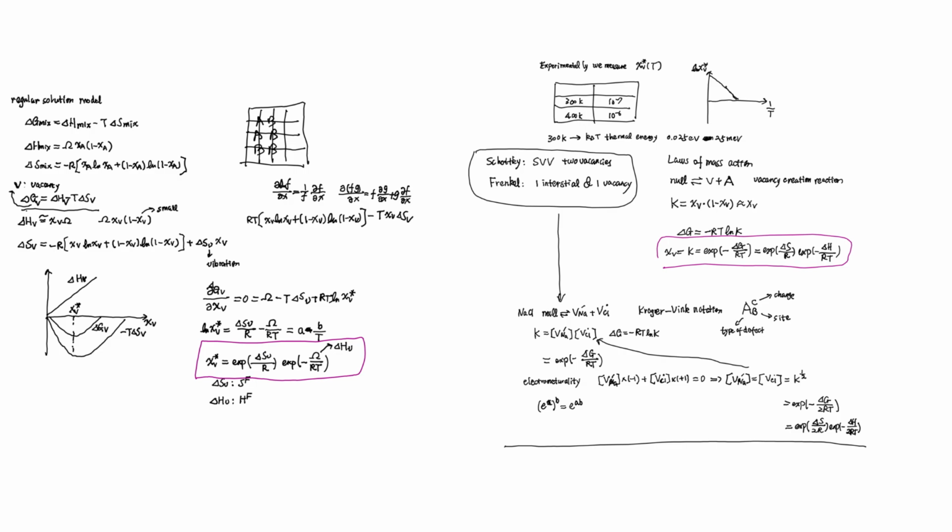So you have a material and you take it to a national lab, because some universities like Bowling Green have a positron annihilation spectroscopy facility. You take it over there, and you measure the composition of vacancy at different temperatures, and you know it's going to satisfy this equation. So now I want to ask you, if that's the case, how do we get delta SV and how do we get omega?